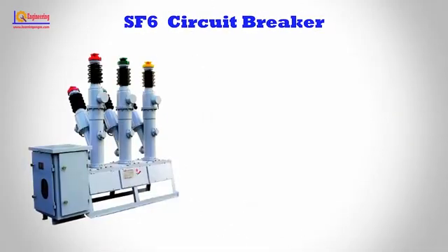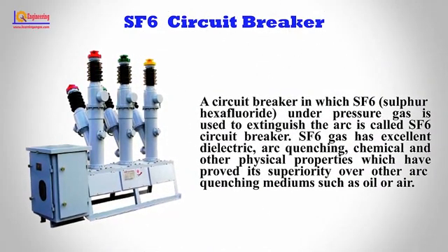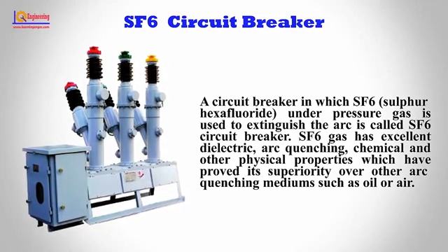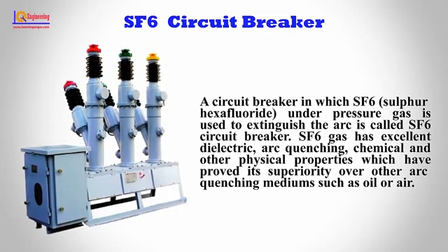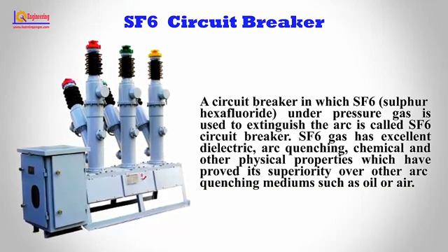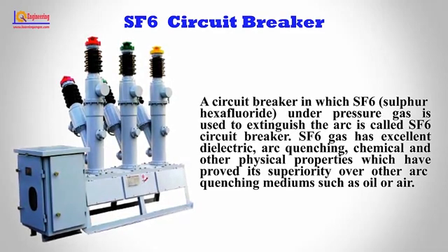SF6 circuit breaker. A circuit breaker in which SF6 under pressure gas is used to extinguish the arc is called SF6 circuit breaker. SF6 gas has excellent dielectric, arc quenching, chemical and other physical properties which have proved its superiority over other arc quenching mediums such as oil or air.